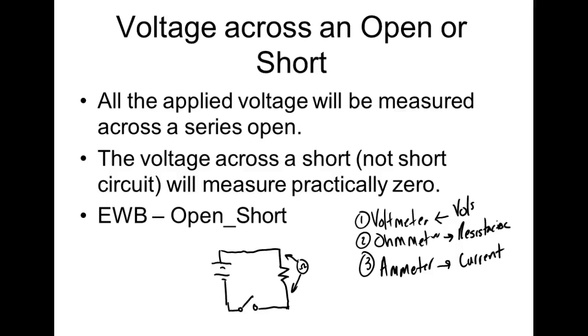And some meters are more forgiving. Radio Shack used to sell a meter called a Micronta meter. And if you ever put that meter in a circuit on ohms with power on it, the meter was gone. It wiped it out. Didn't blow a fuse, it just wiped it out. So you got to be real careful with an ohm meter. They're not designed to be put into circuits with power on.